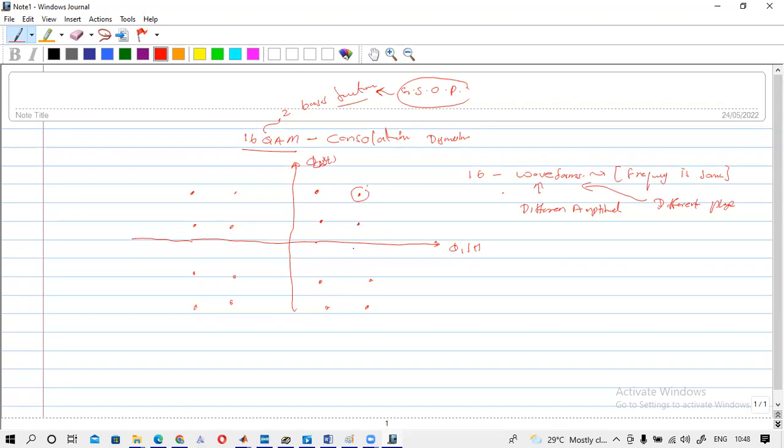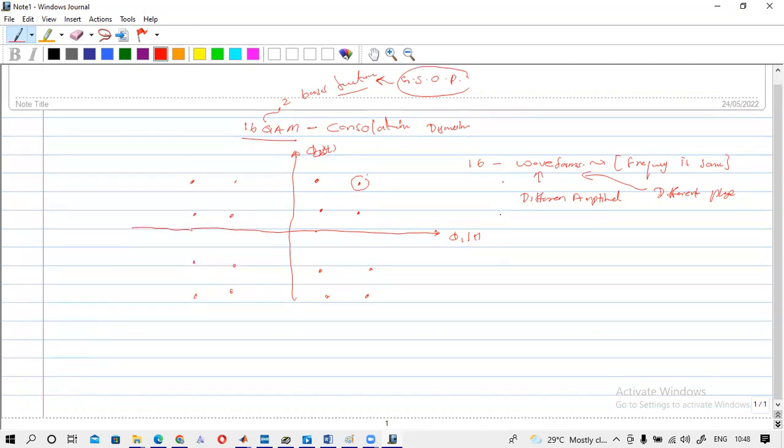Here we are using 16 waveforms. What does that mean? One waveform is one signal or one symbol, so these waveforms are also referred to as symbols. You have 16 symbols. That means in each symbol you will have 4 bits. I think this is okay for you. You will have 4 bits, no?